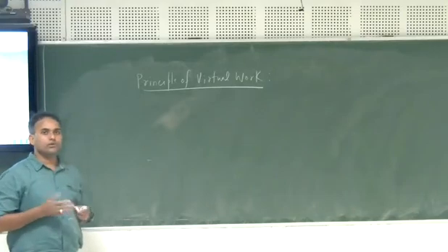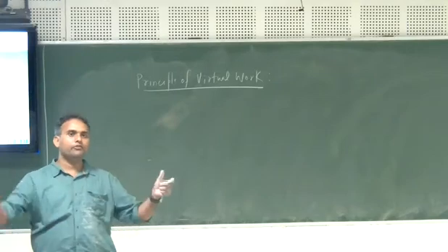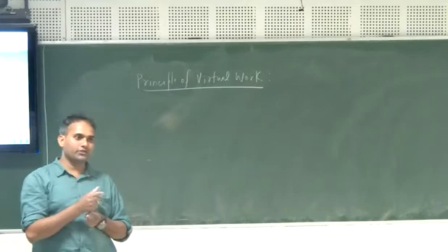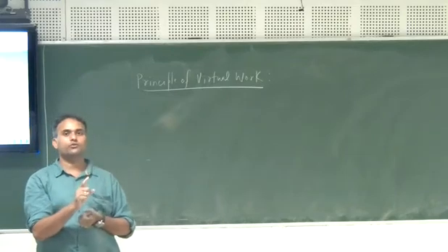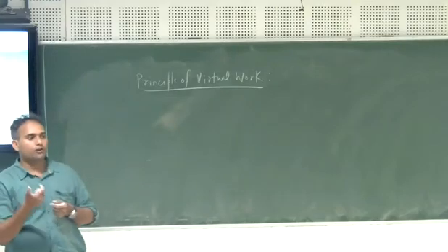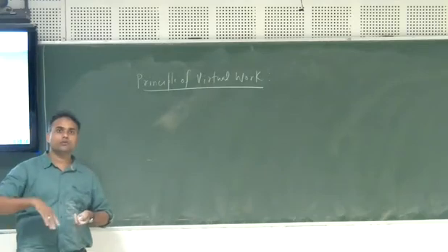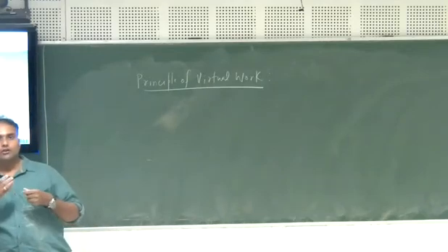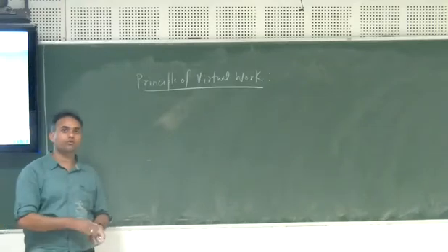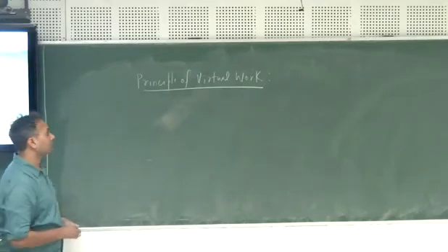So what is this virtual work principle? In this particular principle, you have many forces which are acting on the body. Corresponding to those forces, along the line of action of those forces, you assume there is some kind of virtual displacement. The virtual work can be defined by the virtual displacement times the force. Now the important thing is that those forces should be external.